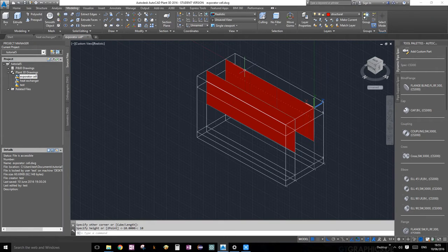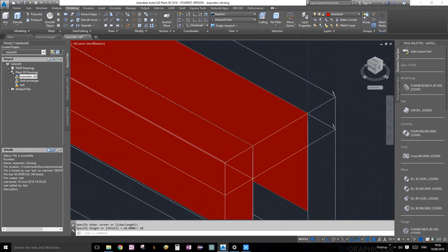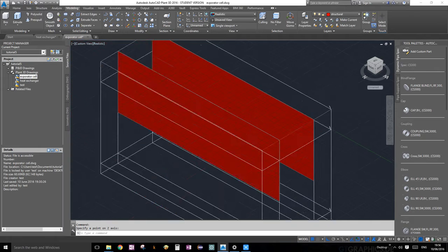Now we just need a top cover here, so we know where the pipes are actually encased, and then the flanges are going to go on top of this where the water would spray on. So again, we need to switch our user coordinate system. We want Z to be pointing upward now. So just grab it, and that's it.